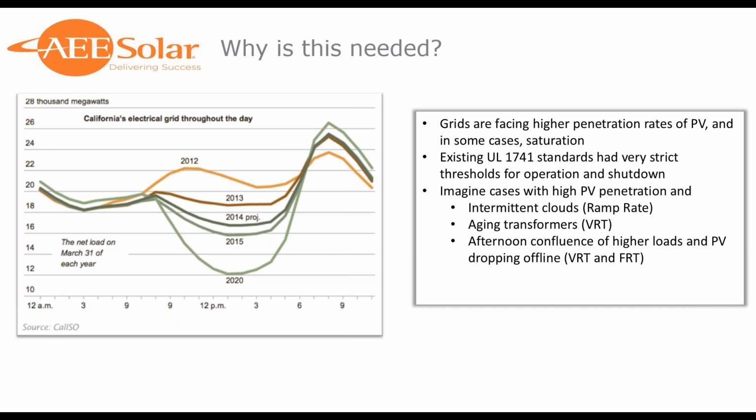If you've ever installed a system at the end of a long feeder, you've probably seen systems where the inverter shut down due to a non-qualified grid, usually because of over voltage, but sometimes because of frequency. So at the end of this long feeder, depending on how that transformer is loaded, you're going to see voltage fluctuation. You're going to see voltage well above or well below nominal.